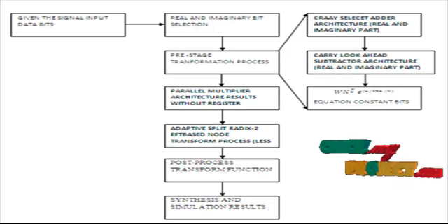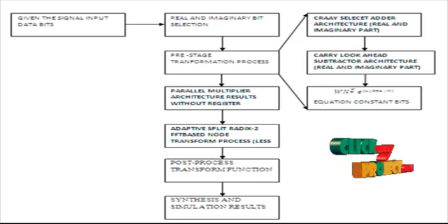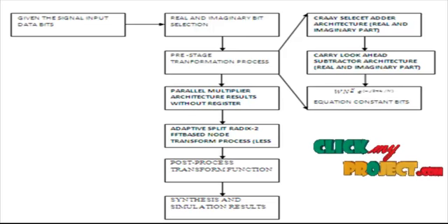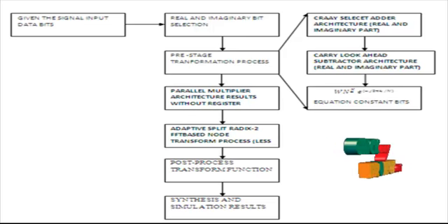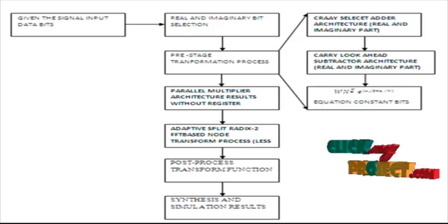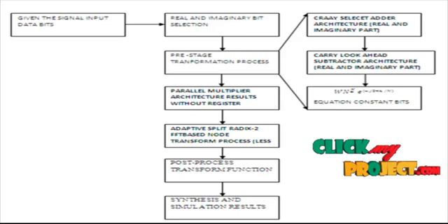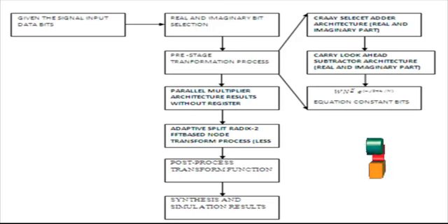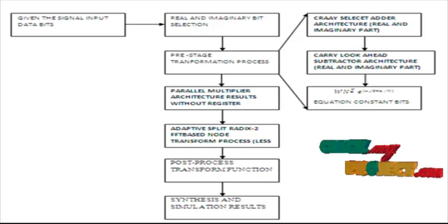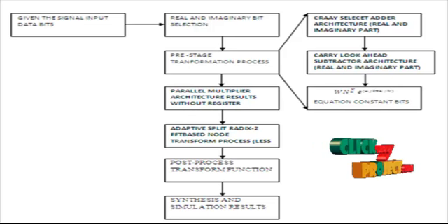Then we pass the adaptive split Radix-2 FFT transformation process for the overall SDC-SDF based input output pipelined architecture. Then we apply this architecture and present the stage by stage output process, and pass it to the post-stage process. This post-stage process gets the final transformation bits for both real and imaginary parts. Then we design all the processes in Xilinx software to simulate and synthesize the overall architecture performance. This level obtains the FFT structure, complexity, timing and power levels also.